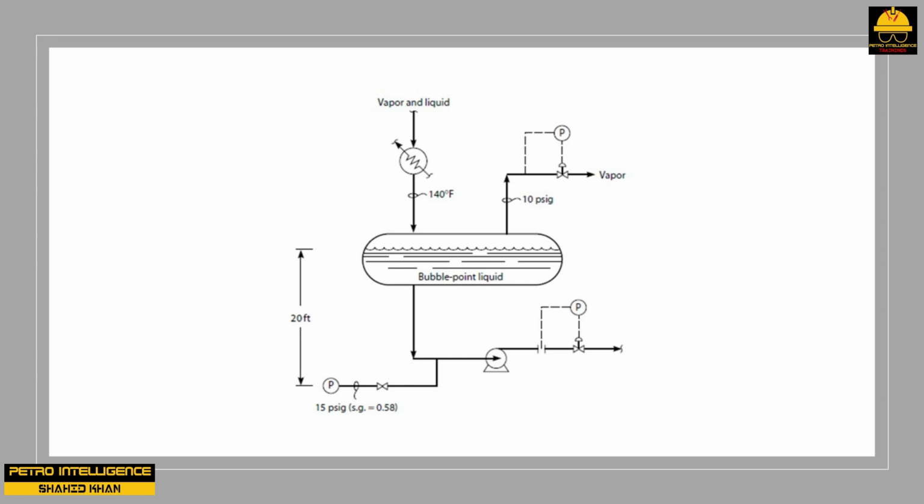Physical pressure at pump suction minus vapor pressure of liquid at pump suction. To express the available NPSH in feet, measure the pump suction pressure and add the barometric pressure, 14.67 psia at sea level. Look up, on a vapor pressure chart, the vapor pressure of the liquid pumped at the measured pump suction temperature in psia. Multiply the difference between the two above pressures by 2.31 feet for water. Divide by the specific gravity at flowing conditions of the liquid, 1.00 for water, 0.85 for diesel, 0.50 for propane at the pump suction temperature.